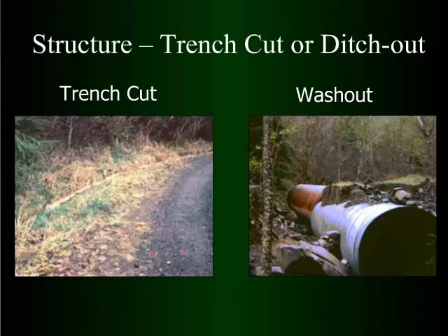Okay, the trench cut, I call them ditch outs. Some people call them blowouts, but where your ditch comes to a point and you want to relieve the ditch water off the road, they usually cut a notch and just basically have a ditch that continues on and disperses the water.